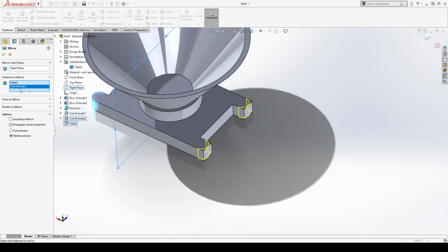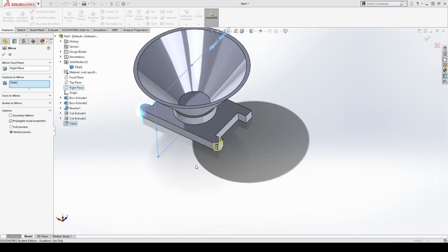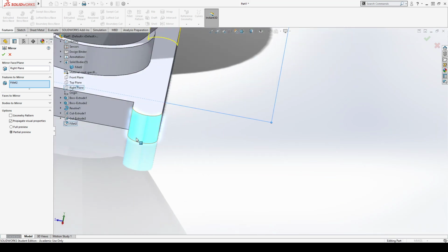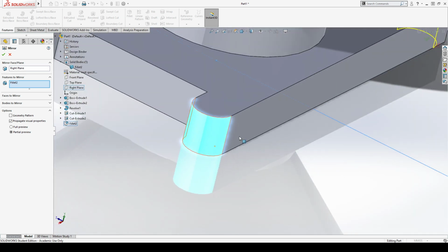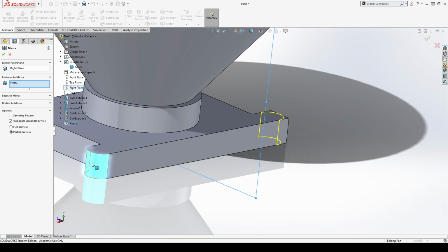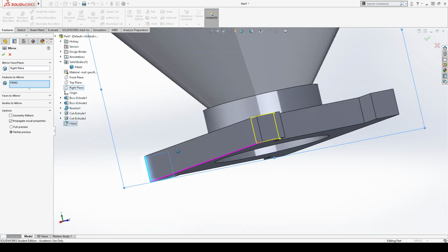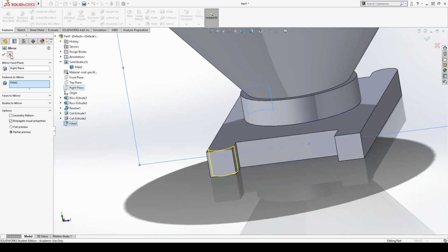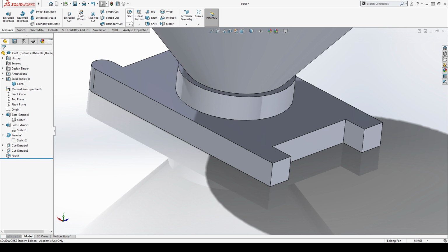All right. So sometimes SolidWorks is picky with stuff. Let's see if it just wants to do the fillet. Yeah. So I guess with these round fillets, it doesn't like doing that for them. Probably because the face that we used for this fillet got modified once we did that, and also it removed this other face over here. So what we want to do is just go through and do that fillet again.